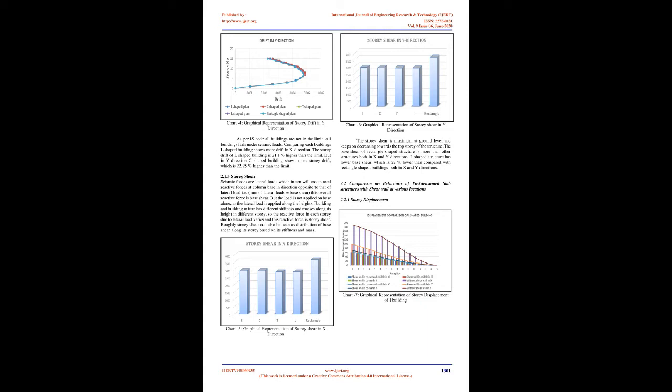2. Results and discussion. Dynamic analysis for post-tension slab building was done using response spectrum analysis for earthquake zone 2 as per the Indian Standard Code. The results are obtained from the analysis of building models and compared for parameters like base shear, storey displacement, storey drift, etc. 2.1 Comparison on post-tension slab buildings having symmetric and asymmetric plan.